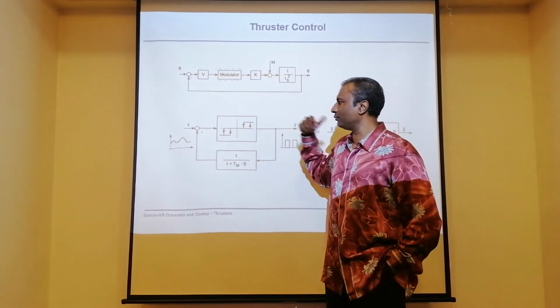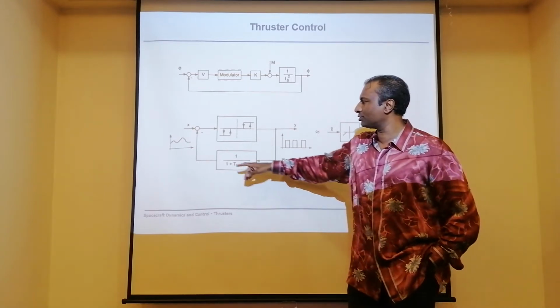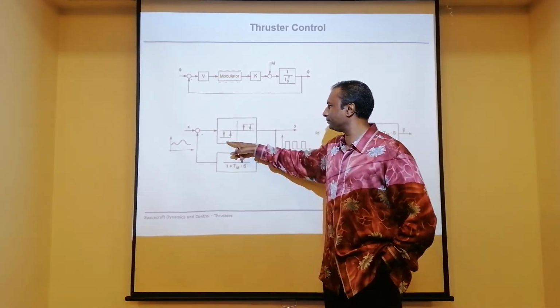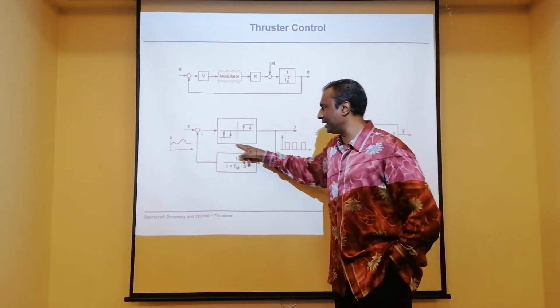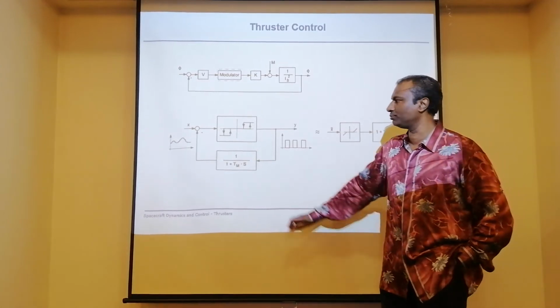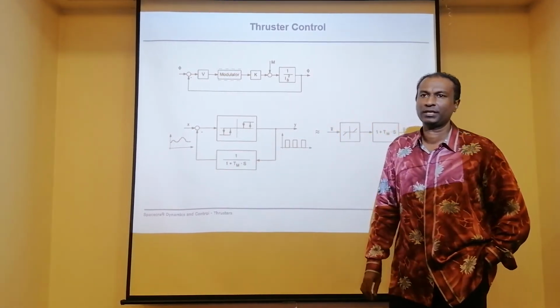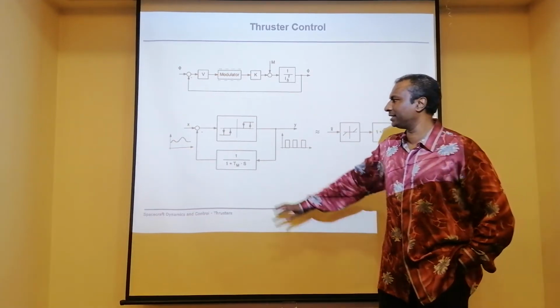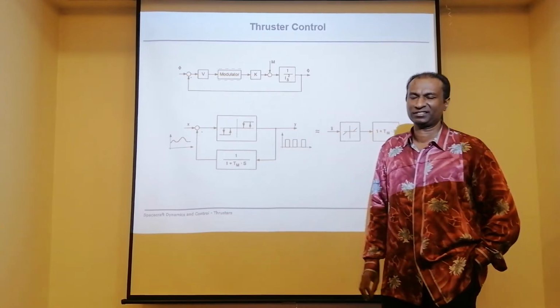No, when we need, we operate. Unlike the reaction wheel, which we operate throughout the mission. Once you turn it on, you don't switch off because that's the active motion. So here we don't use it like that. When we need, we turn it on. So it's always on-off. Then technically you will have the delay. If you have a delay, then it's fine. But if you don't have a delay, then this should be a perfect system. So that depends on the actual model of the exact thrusters that you have.